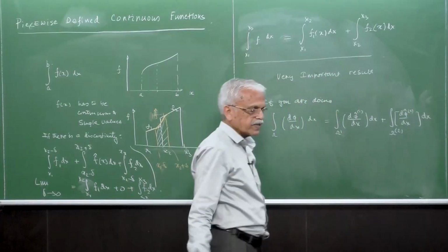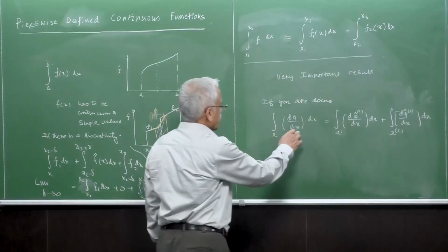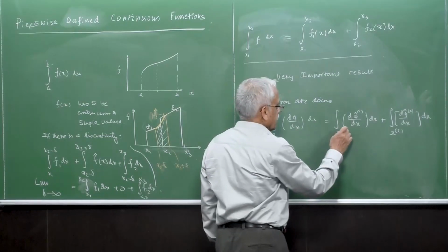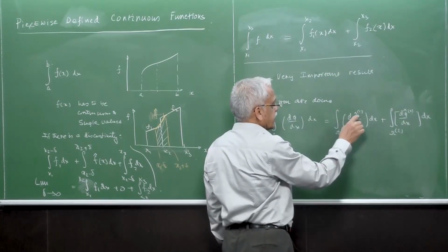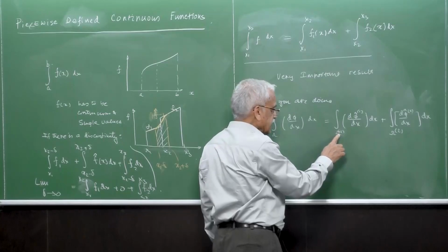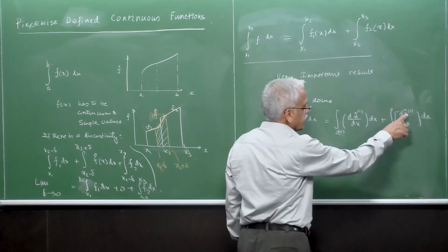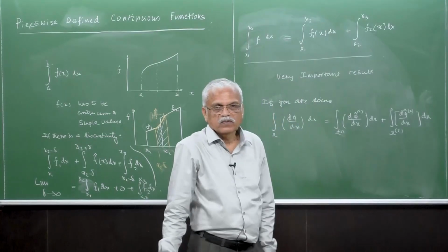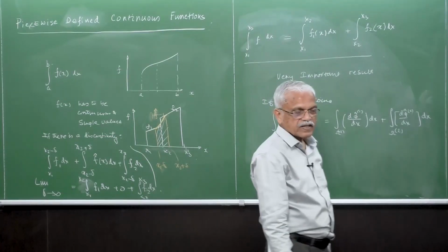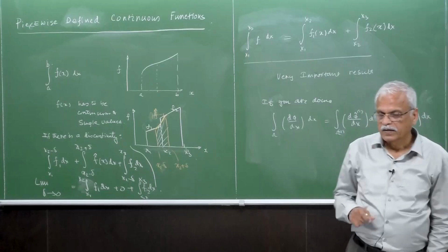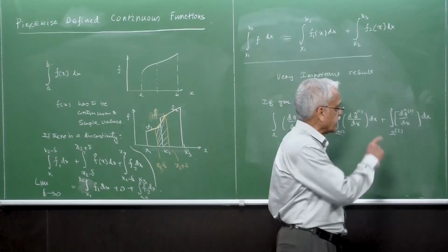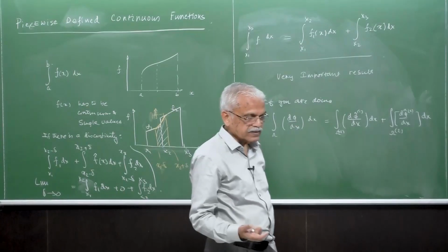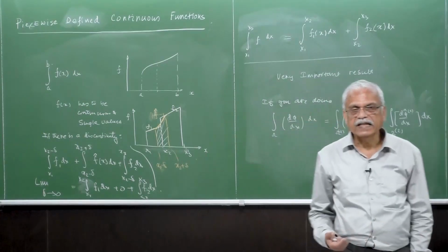So this is a very important result, saying that if you want dφ/dx to be integrated over the whole domain, it is essentially equal to dφ̂/dx as defined in Ω1 integrated over Ω1 plus dφ̂/dx as defined in Ω2. So what happens at the inter-element boundary, that is at x2, is not going to enter our calculations.